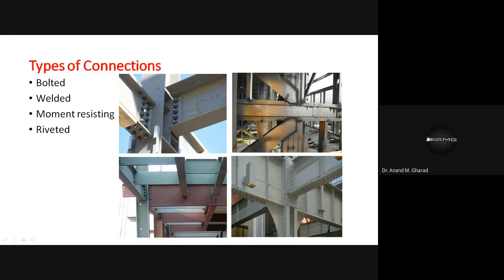So can you see this figure one? In this figure one, you can see the column and the beams. They are getting connected at this junction, which we call a joint, as already discussed. Now this junction is made powerful, or it is given a kind of strength, in order to take care of the moments and shear forces that will be developed. Those will be taken care of by these types of connections in order to make this joint strong. That is, the capacity is increased.